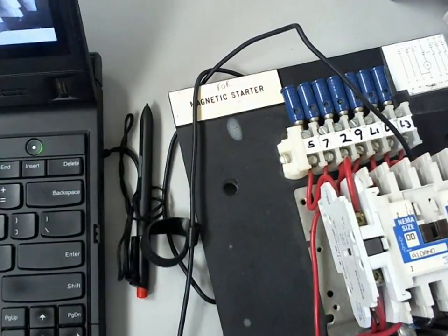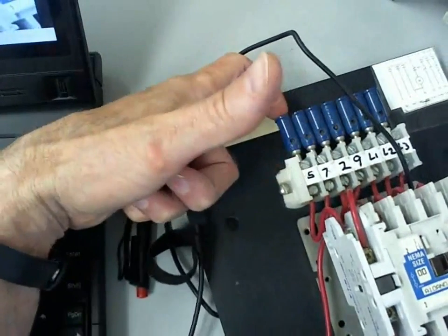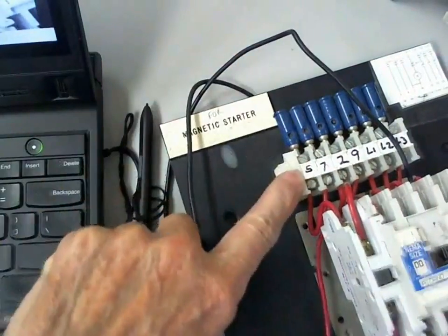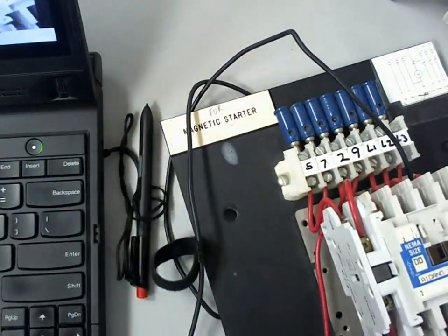Yeah, so this is what we were talking about. My wire number might be 53, but it might hook up to terminal 5 on the device. So terminal 5 was not assigned by me, it was assigned by the manufacturer. When the engineers design my control circuit, they assign the wire numbers.